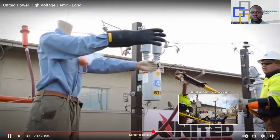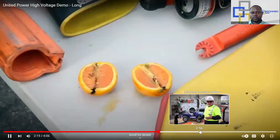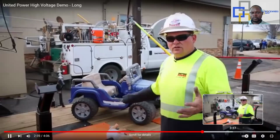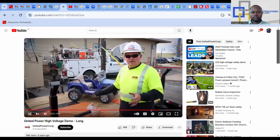The hard hat is for accidental contact in the equipment if you can, or if you're in lethal. If you have to get out, we want you to stand in the doorway and jump out and land on both feet. We call it bunny hop. We want you to hop away as far as you can, as safely as you can. If you can, stay in the vehicle.